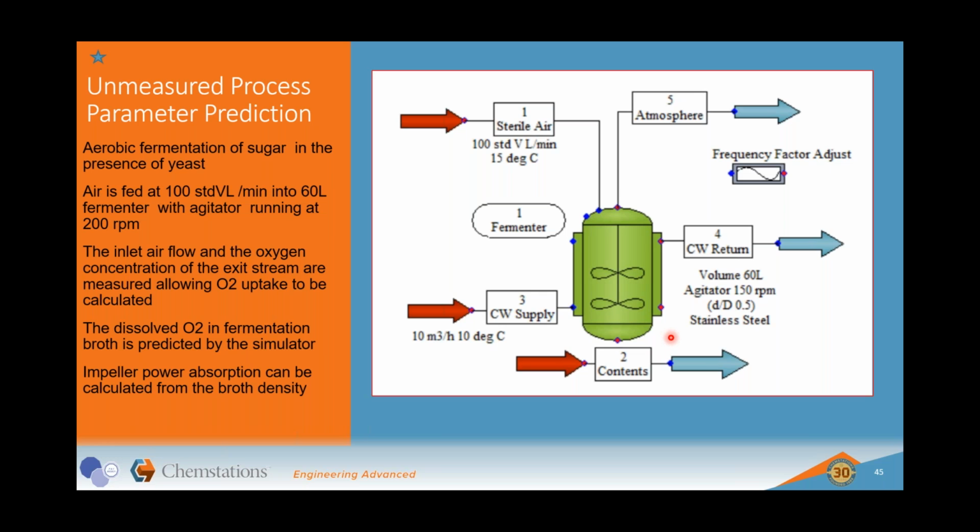If you've got a simulation calibrated and validated against a process, it can be used to obtain data for unmeasured parameters. And there was a plant in Sweden having difficulty monitoring an emission with online analysis. And the calibrated simulation satisfied the regulatory authorities that it was accurately predicting the emission over the total operating range. And it allowed them to stop using the online measurement. So that was a tremendous bonus to this particular company because they were having a lot of trouble with the online measurement.